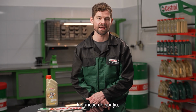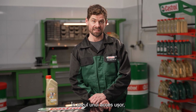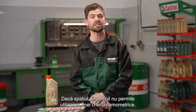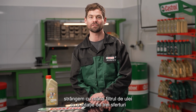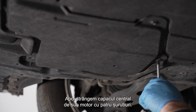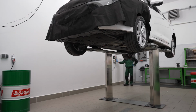Depending on the available space, we can choose one of the following methods. In the case of easy access, you can tighten the oil filter with a torque wrench to 17.5 Newton meters. If the amount of space available does not allow the use of a torque wrench, we tighten the oil filter with a 3/4 turn by hand or with an ordinary spanner. Finally, tighten the center under engine cover with 4 screws. We then lower the vehicle.